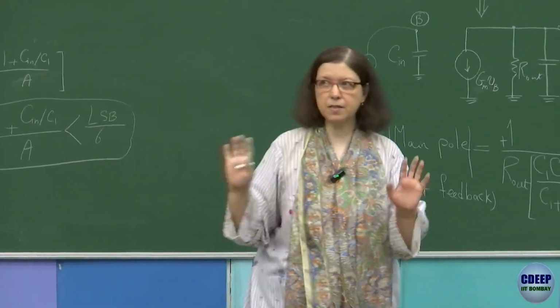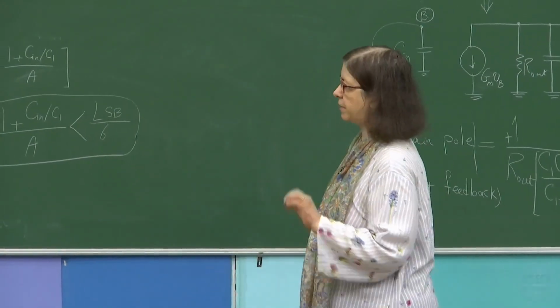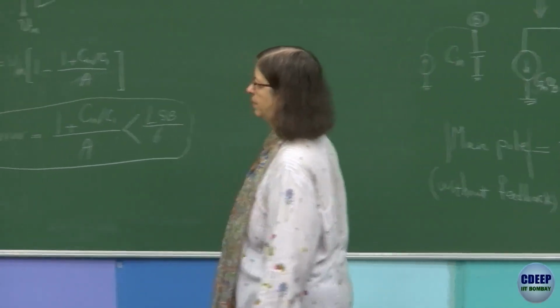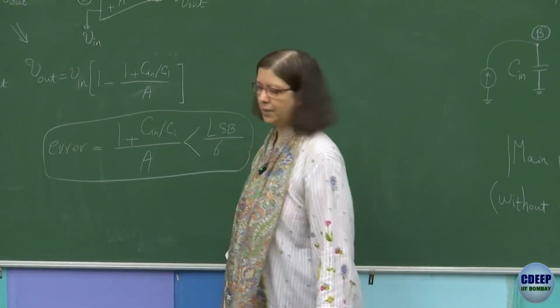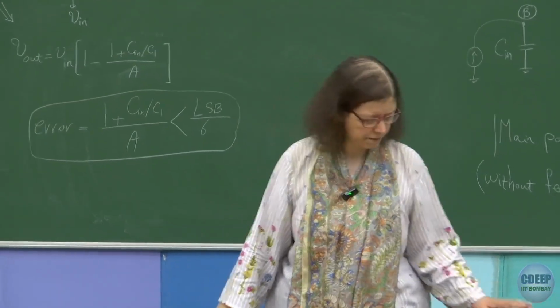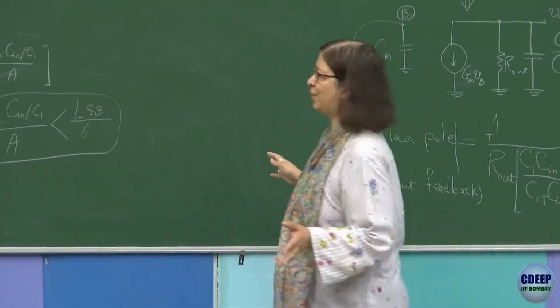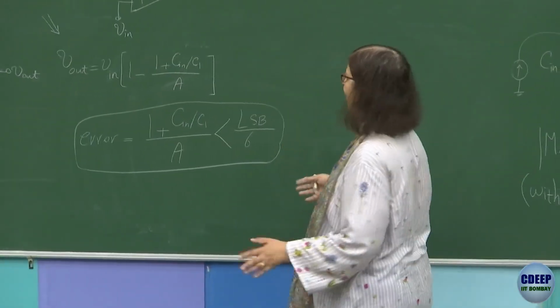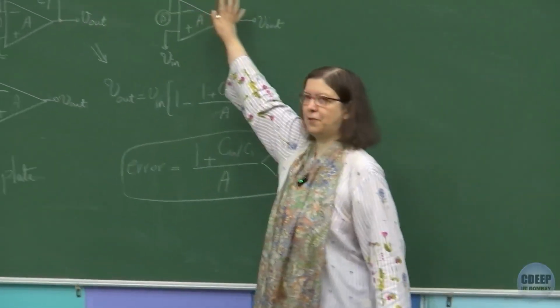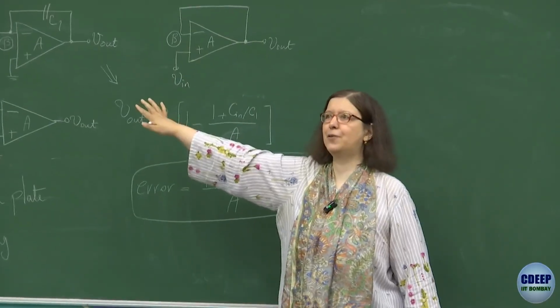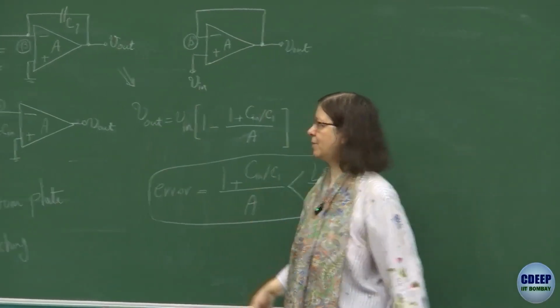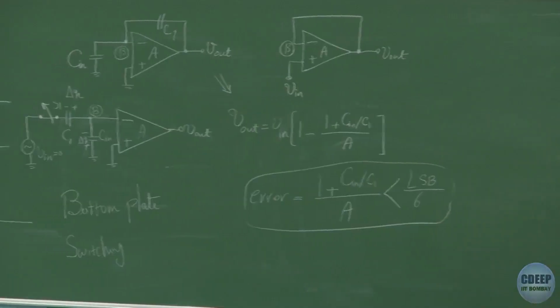Input capacitance upon feedback capacitance. It's a very important parameter in the design. And interestingly, it appears almost everywhere because these circuits are very similar. All of them, at the end of the day, are a kind of capacitive network in the feedback, and a capacitive network at the input. That's why it continuously shows up the same way.